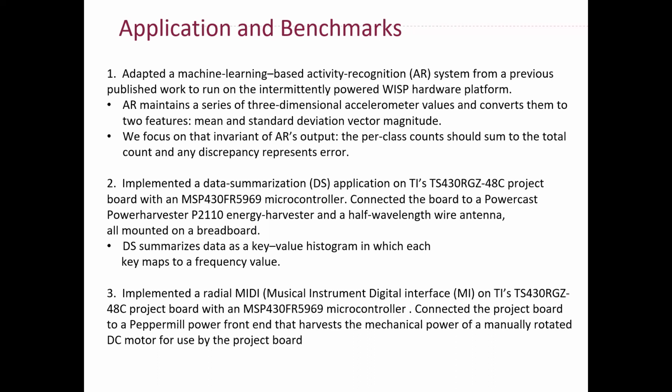They connected the board to a Powercast energy harvester board and a half wavelength wire antenna, all mounted on a breadboard. What DS does is summarize data as a key value histogram, in which each key maps to a frequency value. One function adds a new data sample to the histogram by locating and incrementing the corresponding bin. Another function sorts the histogram by value using insertion sort.